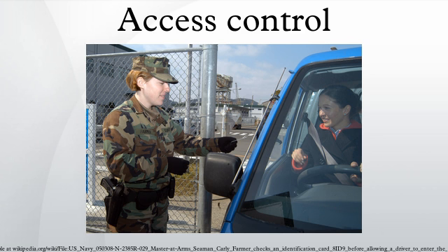The host PC acts as a master on the RS-485 communication line, and controllers have to wait until they are polled. Special serial switches are required in order to build a redundant host PC setup. Separate RS-485 lines have to be installed, instead of using an already existing network infrastructure.